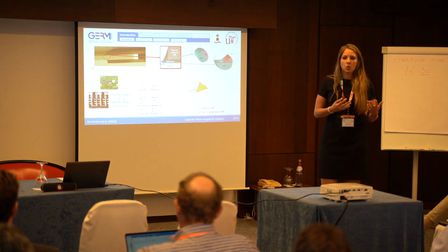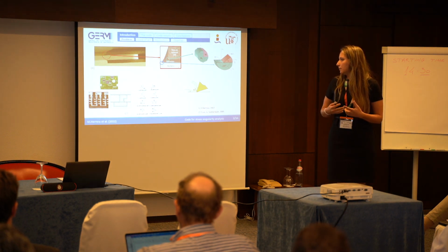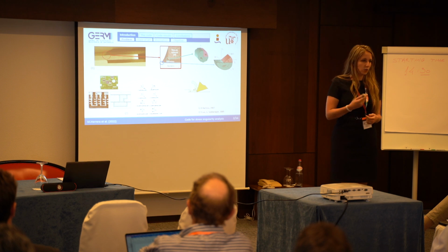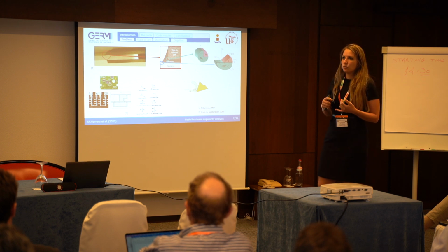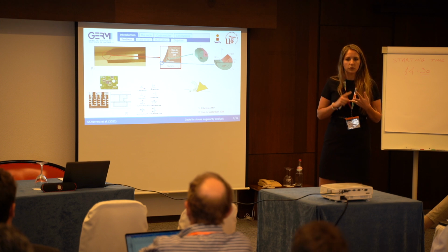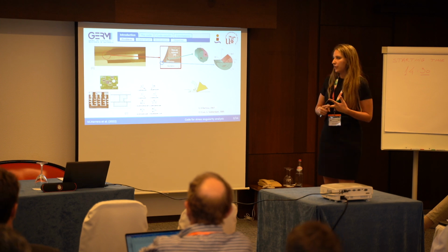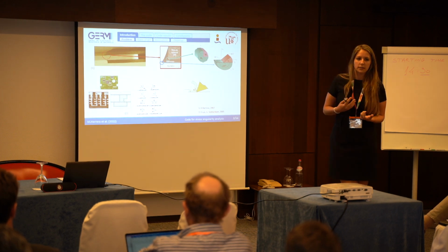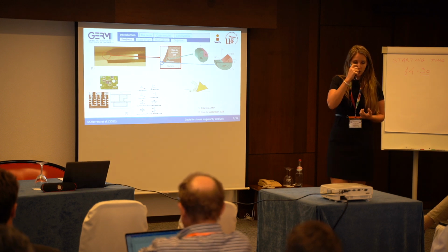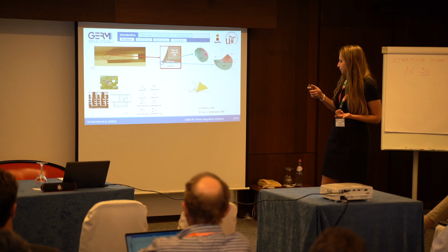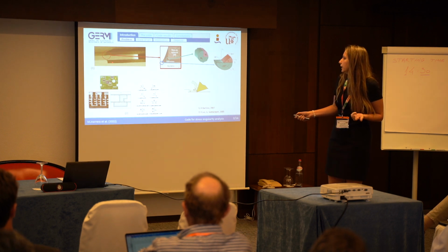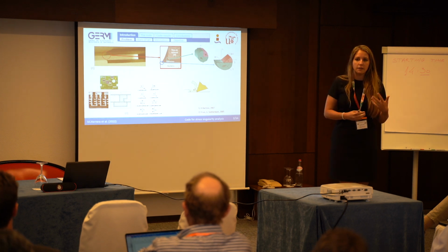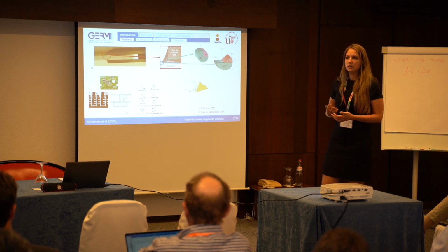As is well known, when several materials with different material conditions meet, the stress field can have a singularity. This singularity depends not only on the material characteristics but also on the boundary condition and on the geometry of the structure. This can be a real problem because you can find this kind of singularity, for example, in the aeronautical industry. This is because composite materials and bonded interfaces are used more and more in this industry.